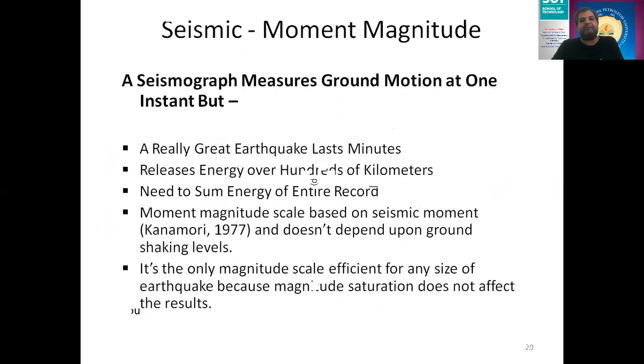This basic limitation is addressed by the fourth magnitude scale, commonly known as the moment magnitude scale, and it is widely used in the world. Whenever I refer to magnitude, it means the moment magnitude scale. To put all these magnitude scales on a common platform, you need to convert MB, ML, MS, whatever magnitude scale you are using, to the moment magnitude scale. So let's see what exactly the moment magnitude scale is.